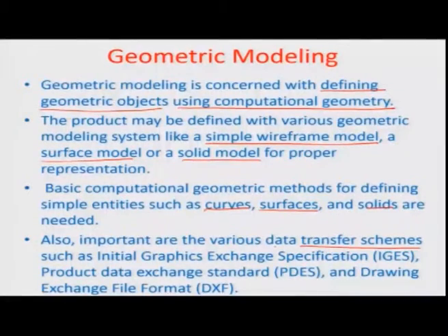For that there are certain data transfer schemes which have been set up internationally, and people designing CAD platforms generally follow such schemes. One of them is, for example, the Initial Graphics Exchange Specification, IGES, or the Product Data Exchange Standard, PDES, or the Drawing Exchange Format, DXF. Most of these you use in your normal methodologies while handling CAD.